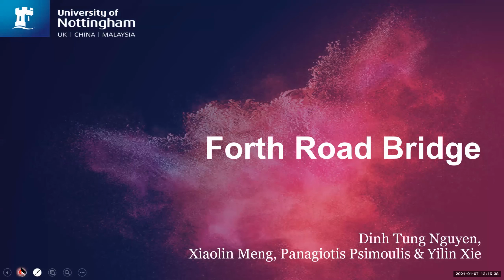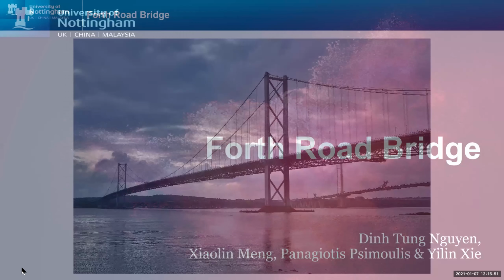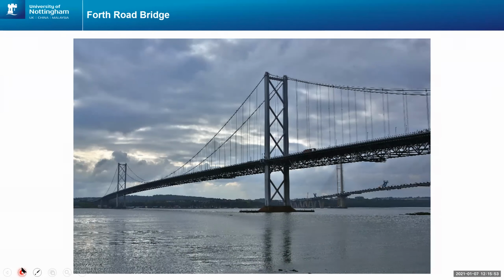Okay, so that was a very quick overview of some of the lessons that we learned from the monitoring of the Keswick Bridge, which really first got me into wind engineering. Now let me introduce some work that we've been doing on the Forth Road Bridge. As you can see, the Forth Road Bridge here in this image, it's a very different bridge to the Keswick Bridge. It's longer, it's a suspension bridge. The deck is a big open truss girder, and therefore got very different